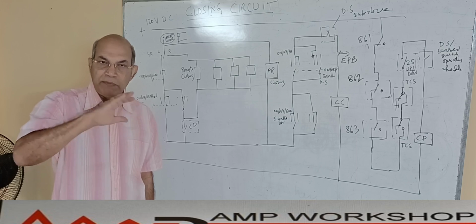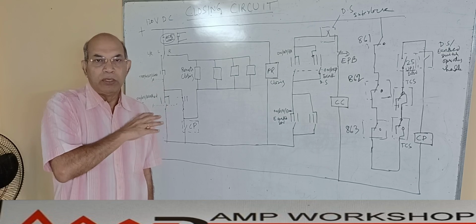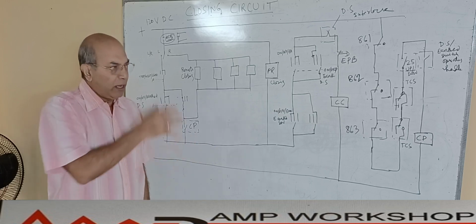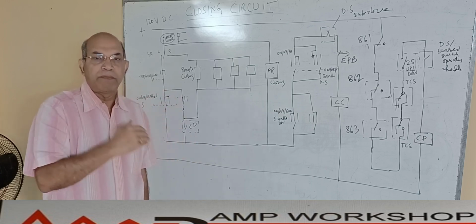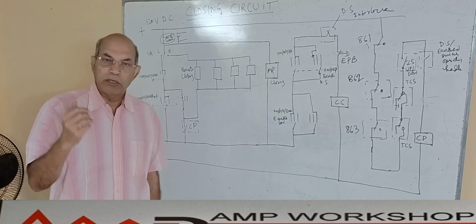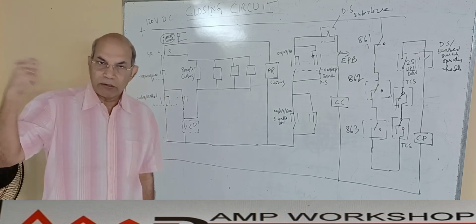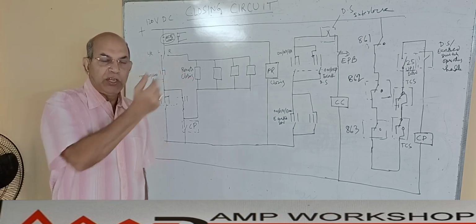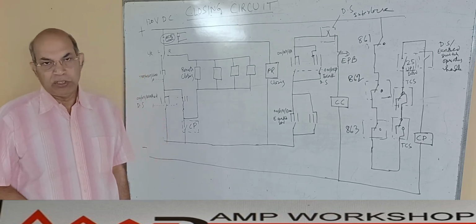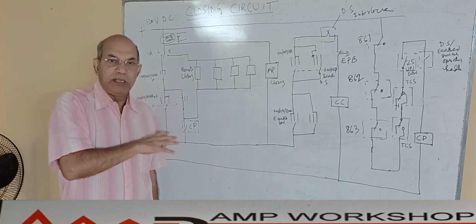Except this position, if there is any other position from where this switchgear is getting controlled, this switchgear means this particular feeder panel or the general incomer panel, but any one of the panels is getting controlled from the remote, then that position will be called the remote position. Now the remote could be different positions. It could be a control room, it could be another control room, it could be from the process area, it could be from the remote receiving station, it could be different. Any other except the local position means switchgear position.